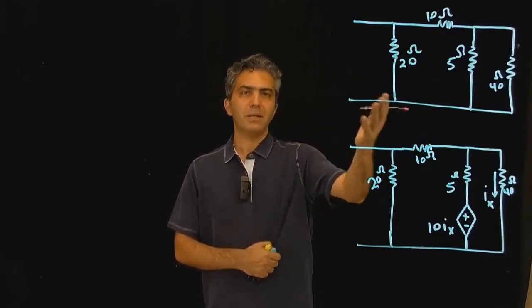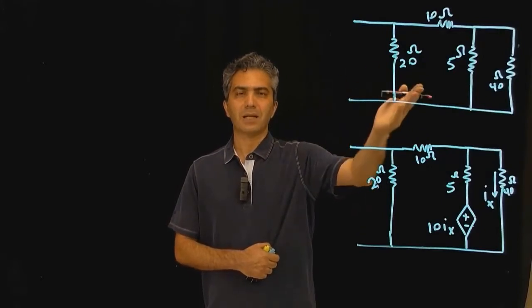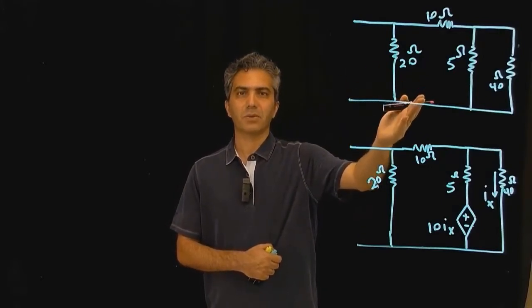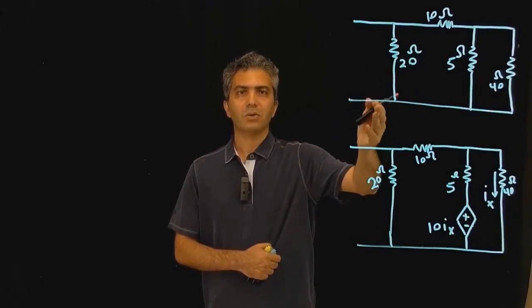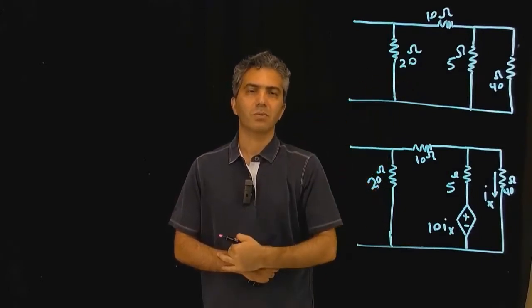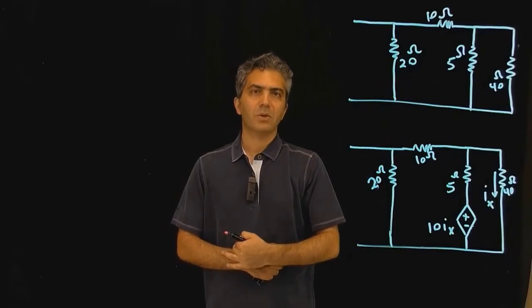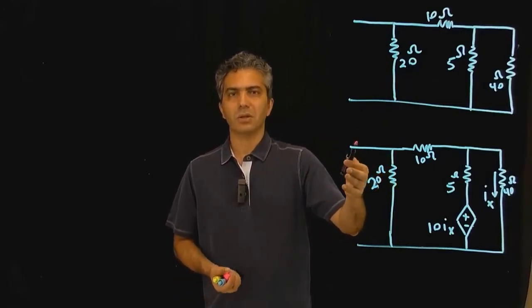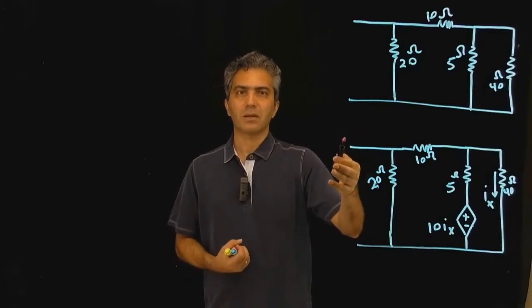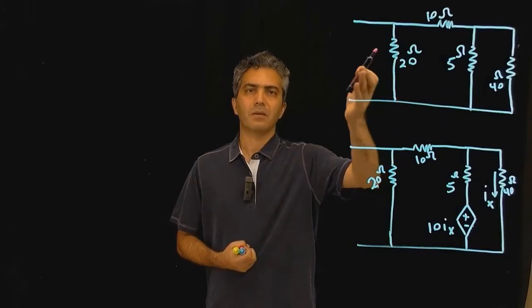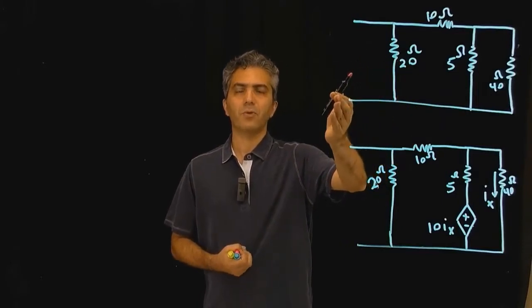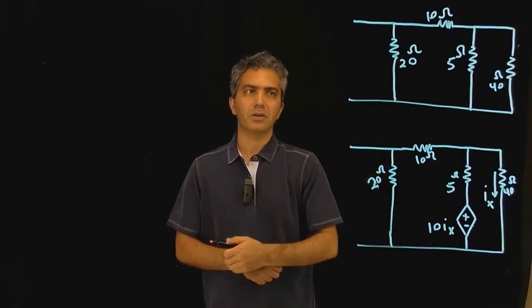So based on that, if I am tasked to develop a Thevenin model for this one, or Norton model for this one, V Thevenin or I Norton for both of those would be 0. There's nothing wrong with that question, as long as we realize that since there is no independent source of energy here, the Thevenin voltage or the Norton current are 0.